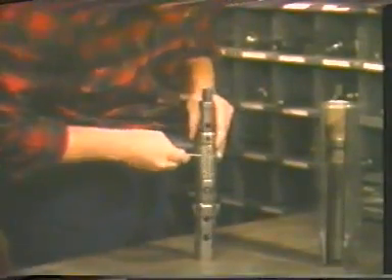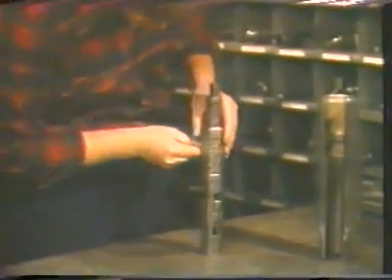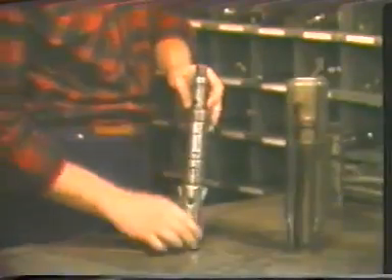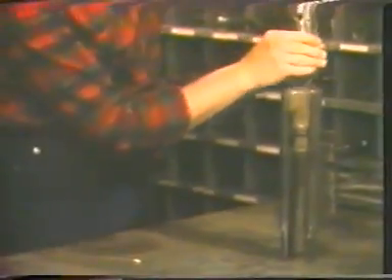If the lock assembly is to be run to the uppermost F nipple of its size in the tubing, a locator ring, which will no-go in the nipple, is threaded onto the running tool. The lock is then lowered into the well bore on wire line until the nipple is located with the locator ring. Pulling the tools up allows the up-facing locking dogs to snap into the nipple profile.